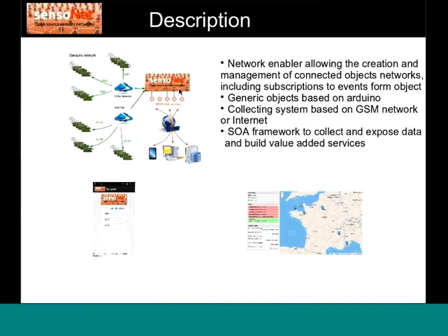On Arduino it's hardware, so it's very often very low-level libraries. For example, if you want to send an SMS, you have to read and send byte per byte to a modem with AT instructions. It's very painful. The idea of Sensonet is to provide a high-level library where all this communication is completely managed by the library and where the developer will only focus on his main code.